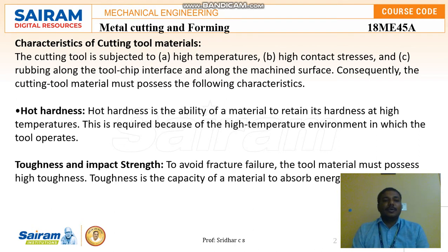Next, the material must also possess the following characteristics. First one is hot hardness. Hot hardness is the ability of a material to retain its hardness at a high temperature. This is required because of the high temperature environment in which the tool will be operating.